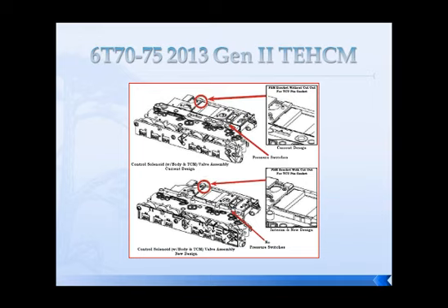The solenoids are also different. We've gone from normally low to normally high solenoids, so bottom line is we've got some that are controlling feed and some that are controlling exhaust. So you cannot interchange these TECMs because you're going to get yourself in real big trouble. Even though the bolts would bolt up, you don't want to do that.